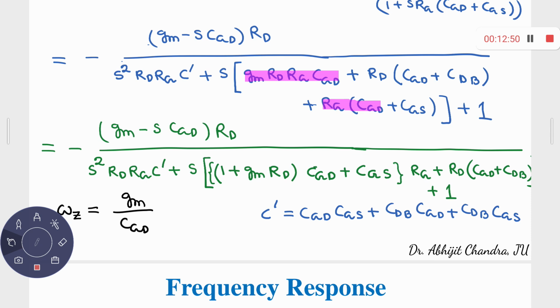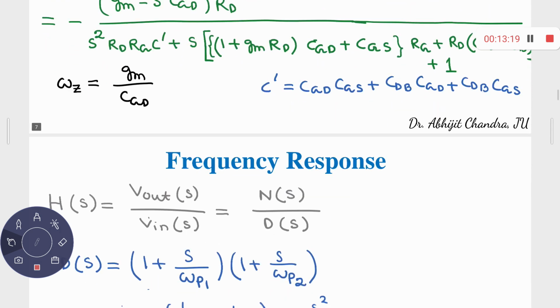this corresponding omega, what is the omega expression? Suppose on the input side you have some omega, let me call it omega p in, the pole frequency omega p. What is that omega p? That is nothing but 1 upon RC, R effective, C effective, on the input side. Similarly, on the output side you have 1 by R out effective, C out effective. So once you identify those nodes, let me move to that particular analysis.